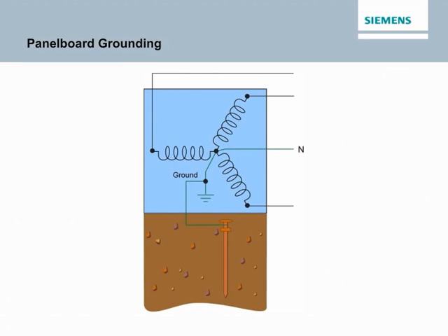Grounding is an important aspect of any electrical equipment and must be considered carefully. A ground connection is a connection to earth or to a conductive object that is connected to earth. The accompanying illustration, for example, shows the neutral conductor of a Y-connected transformer connected to ground. The intentional grounding of electrical equipment is done to limit voltage differences between parts of the system. This is necessary for the safety of personnel and the protection of equipment and facilities. Article 250 of the NEC covers grounding and bonding requirements for electrical installations.